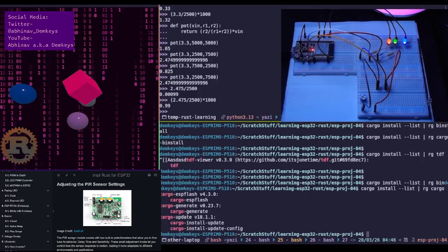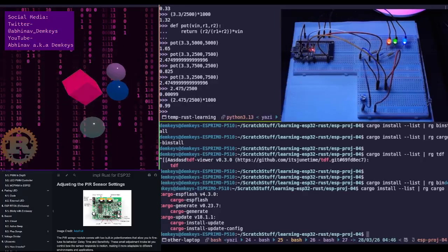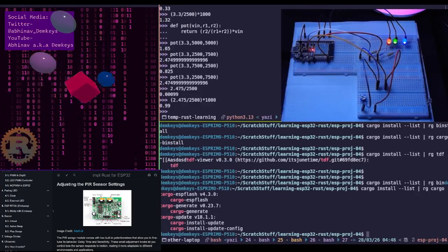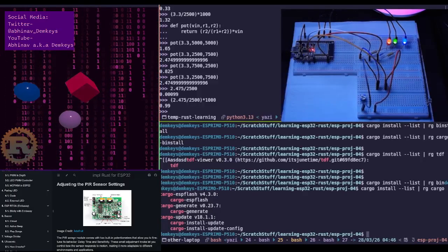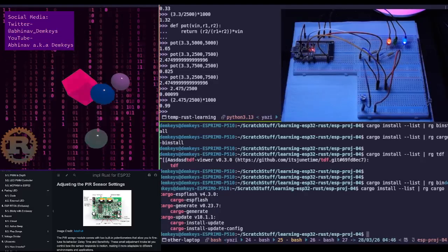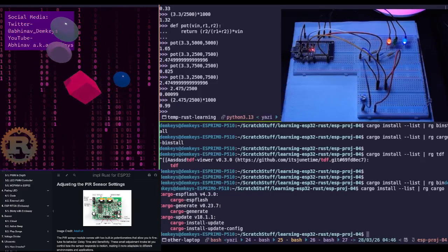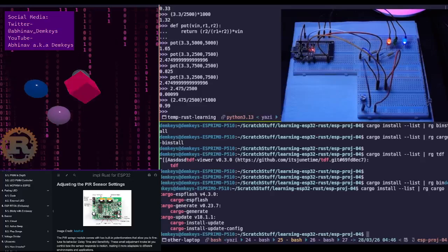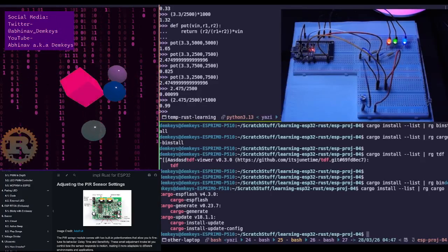If I solder header pins on and then place the thing on the breadboard, I'll need to make sure that the display itself is sitting on the breadboard and not hanging off of the header pins in any way. I don't know how to explain that, but I need to make sure that doesn't happen, because eventually that's going to damage both the pins and the breadboard holes.